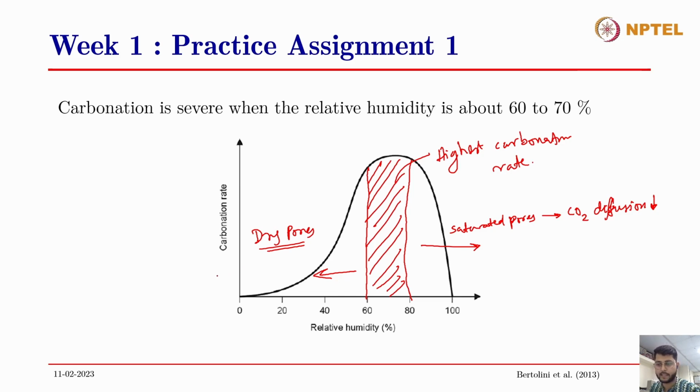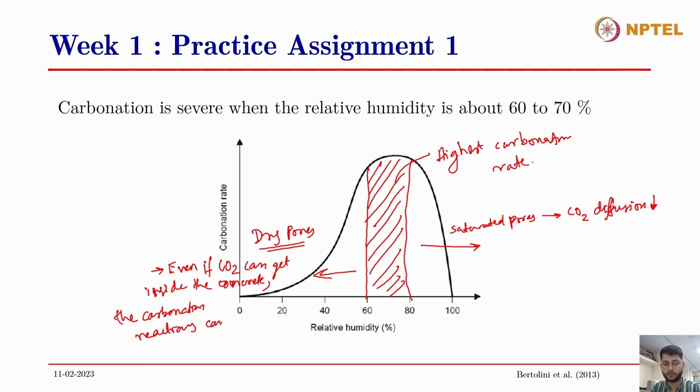The alkalinity will get decreased. So in case of dry pores, even if CO2 can get inside the concrete, the carbonation reactions cannot take place.